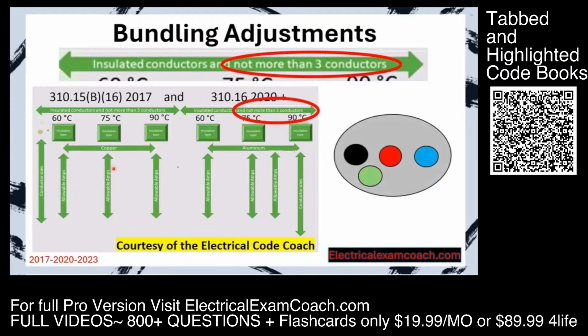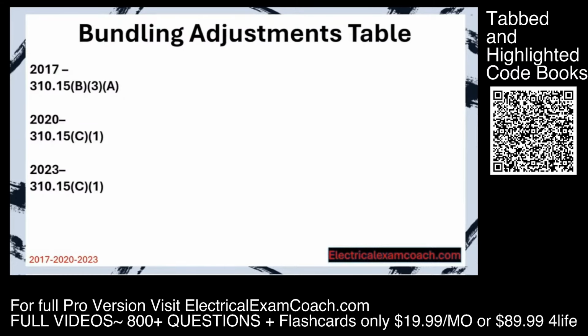Let's take a look at it. Let's imagine that we have a piece of conduit here and we pulled in a black, red, blue, and an equipment grounding conductor. What this table is saying is that those ampacity values listed down below in this table are true as long as you have not more than 3 current carrying conductors in a cable, pipe, or raceway. If you do have more than that, then we have to do what's called a bundling adjustment.